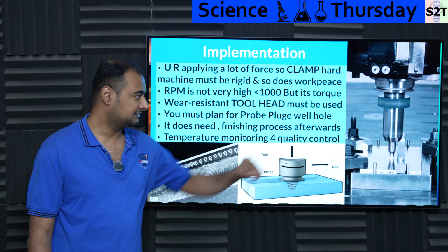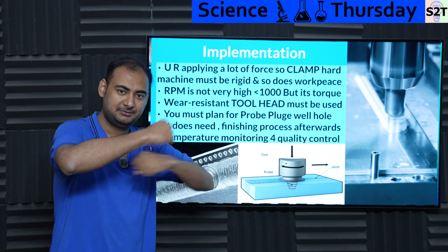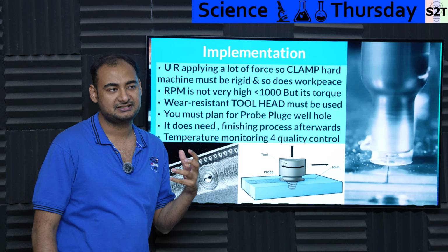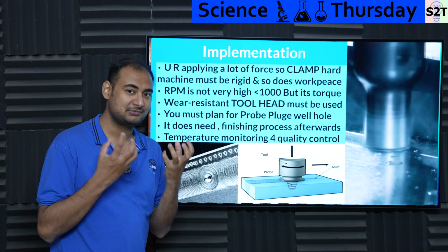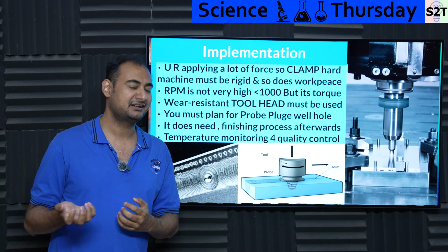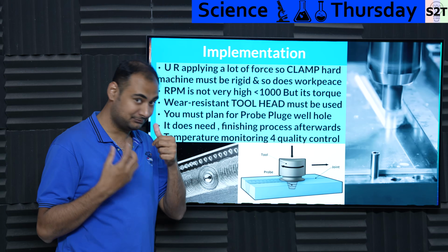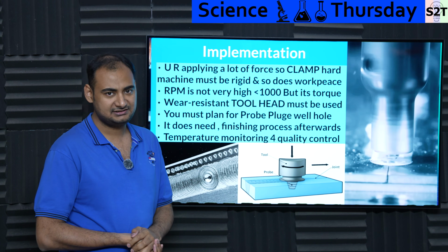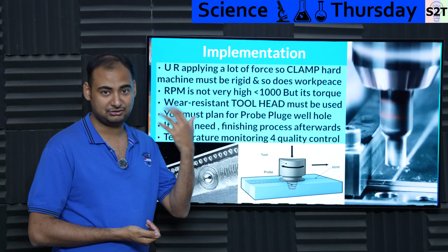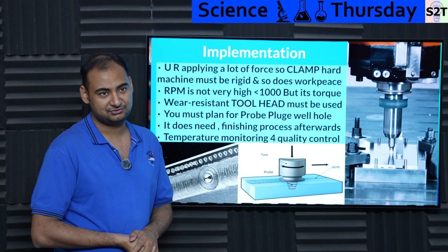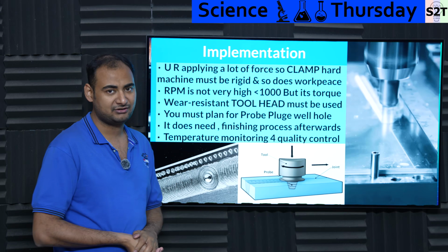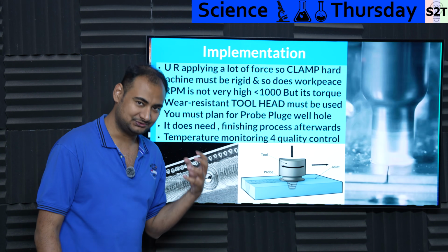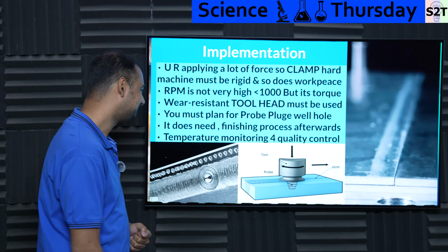And the tool head, the thing that is making this marriage, is generally made out of material that is abrasion resistant, because again, you are talking about metal grains. It will sand away any material. So it has to be abrasion resistant and temperature resistant. Generally for aluminum, hardened tool steels are a good choice. And if you have to deal with steel, carbide could be utilized, or certain types of ceramics. It does require a certain level of physical oomph, like you are physically brute forcing it. So you better be strong to do this.